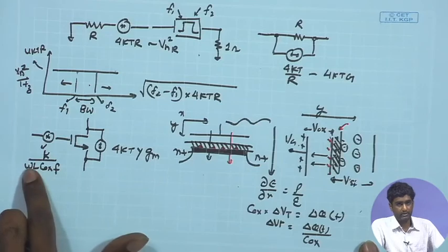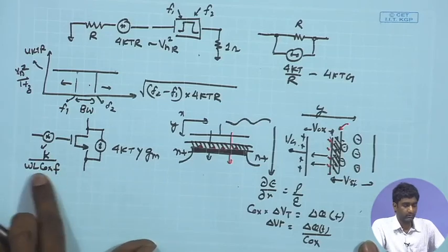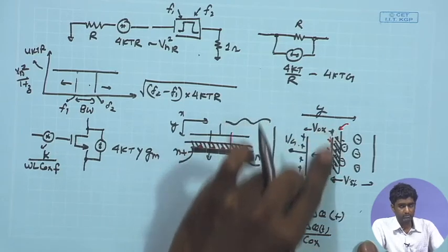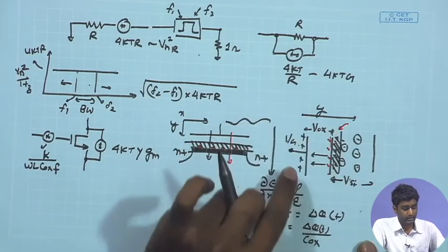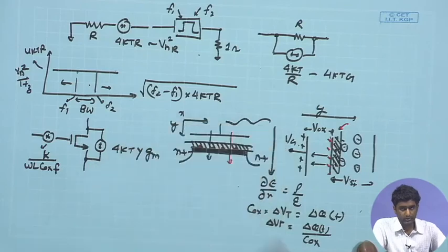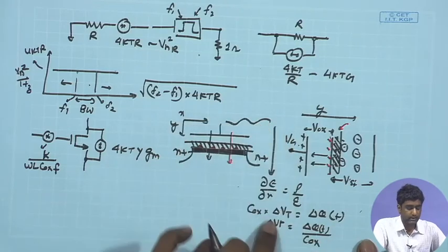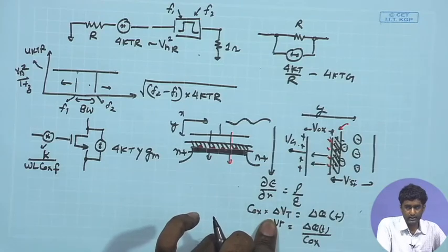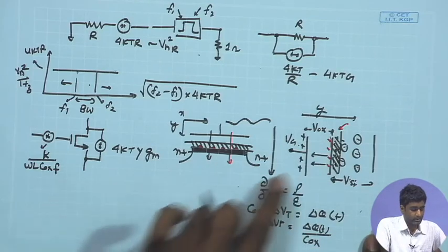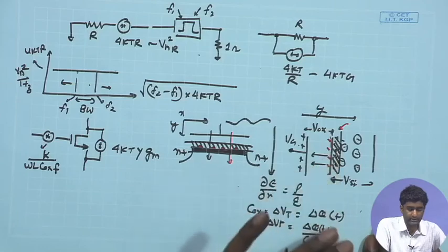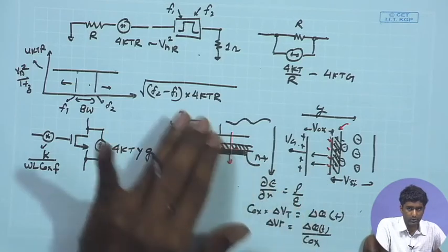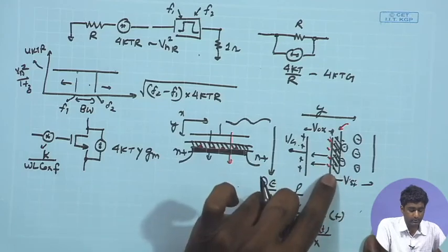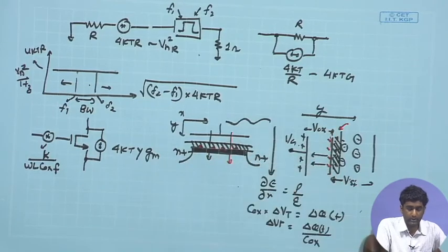and then we have other terms coming over here, the 1 upon f term, W and L terms. Why 1 upon f term? Because this trapping detrapping process is in general a slow process, and if your signal over the gate is changing much more slowly, the trapping detrapping process will be able to follow that signal more closely. As a result, the frequency component of the noise is more towards lower frequencies. As you go towards lower frequency, the frequency content of the 1 upon f noise increases.